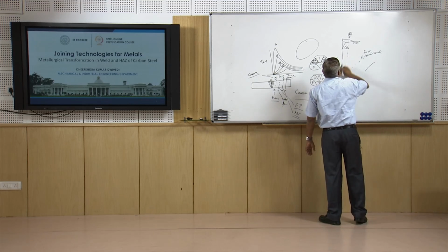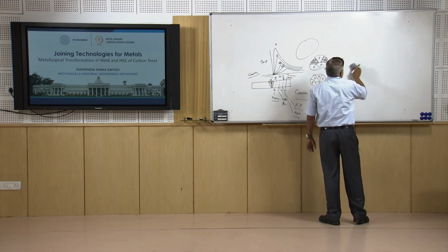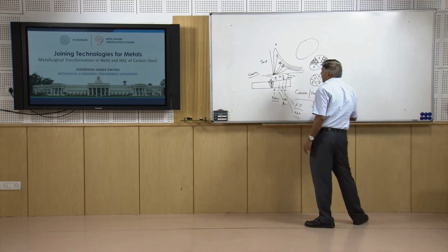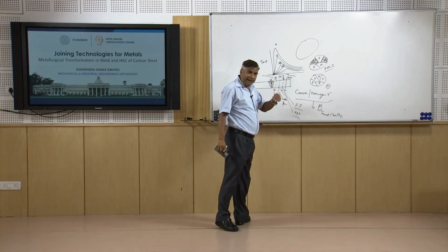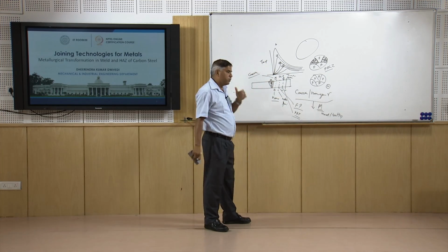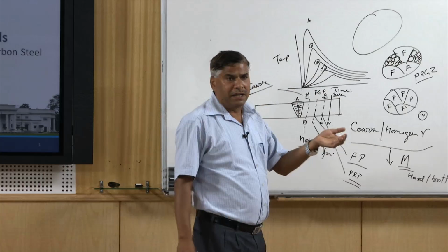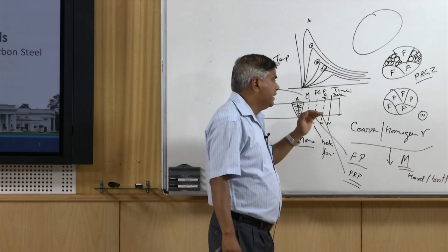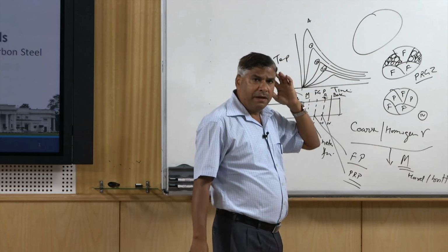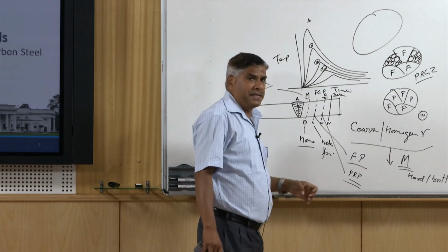Further, if very heterogeneous austenite is formed, where due to the lack of time the pearlite, which is of higher carbon content, transforms, then during the subsequent cooling phase of the welding, high carbon austenite formed as a result of the transformation from pearlite to austenite will result in high carbon martensite also.